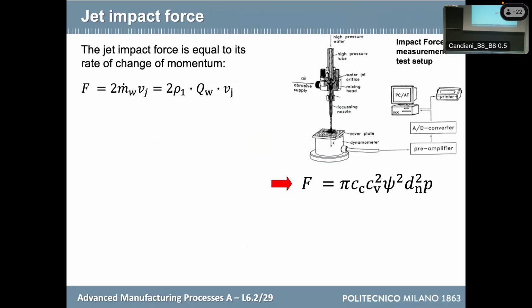Instead, when I'm drilling, I have the push of the water, and water is not able to cut by itself. Okay, it is pushing, just pushing. And if I have a composite material, I risk to delaminate, because the water will infiltrate in the layer, especially if the carbon fiber is not good enough. You know that carbon fiber has a different quality. The bad quality is when you have voids, you have spaces between one layer and another. When it is really dense, in reality, the jet passes through.